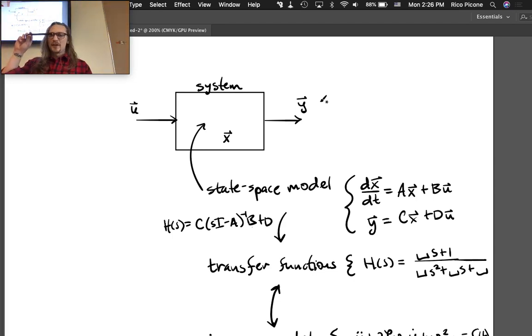If you understand the system's dynamics really well and you have a good model for it, you can figure out what input you need, like how much torque you'll need, to take it from 0 angle to 60 degrees. Great. If you know the system perfectly and you did a great job of modeling, you got it.